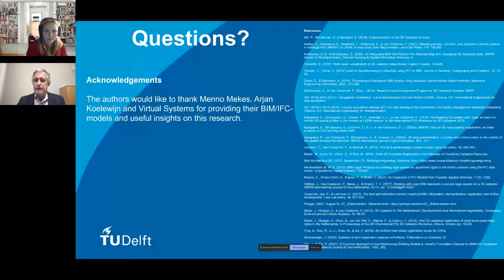And the next question is of a more technical nature. FME can convert all types of geometric representation in IFC to PostGIS, OGC. IFC has so many ways to model 3D. Yes. If I'm looking for the question, yeah, but that's actually an issue. FME can transform a lot of formats to other formats, and it's hard to choose the right one. And also, especially for validating the models, some validations in PostGIS and FME only work with a certain geometry type. But then you also have to look, am I using the right geometry type? Am I using the right validation? And yeah, is the result really what I meant it to be? So yeah, IFC has many ways to model 3D.